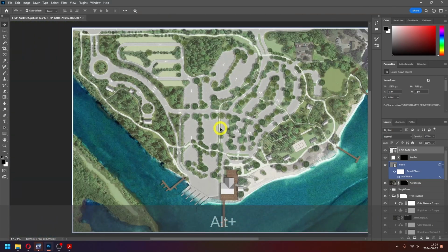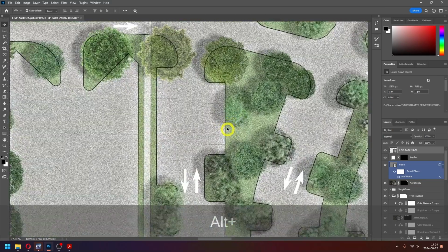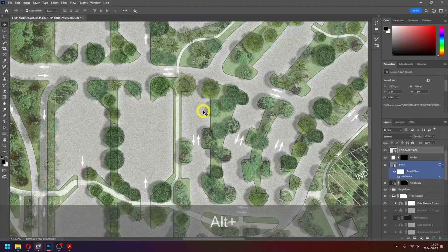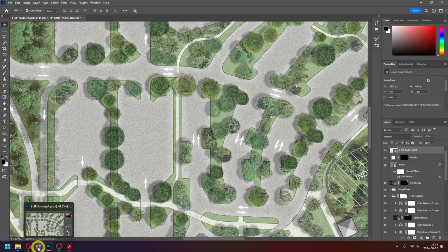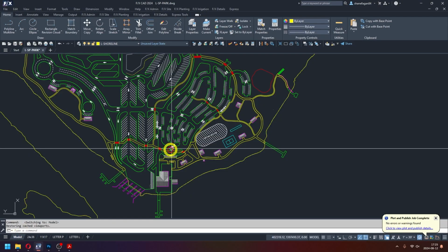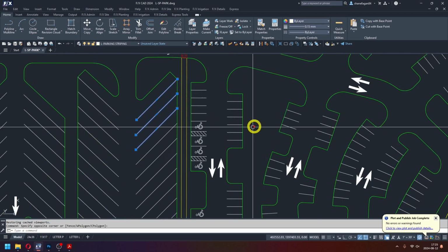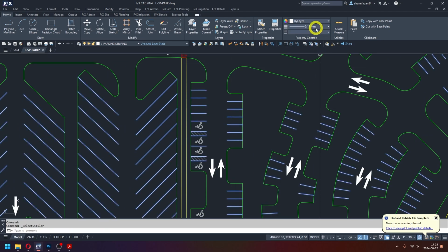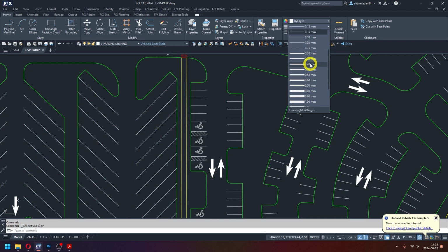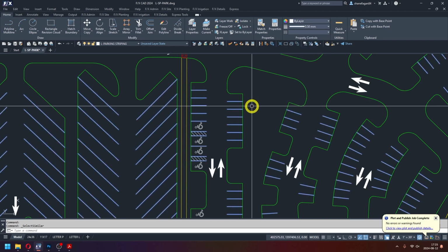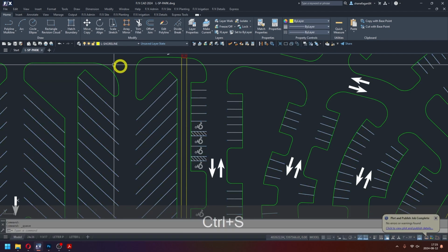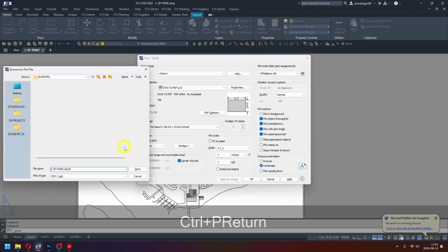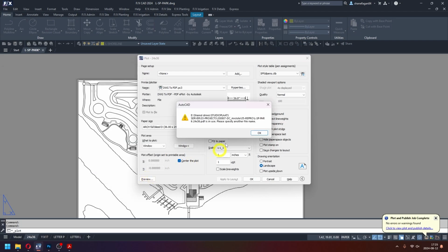line weight. Once you get to the finish, if you go, oh, you know what, actually, I think these lines need to be a bit darker or a bit bigger as well, you just go back into your, here, we can even do that. Go back in here. Select all this stuff, select similar. Let's make it almost 3 times as big. Go to our layout, print, done, save.